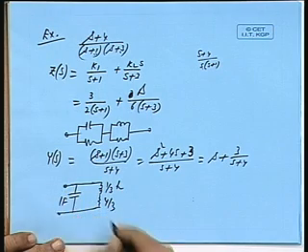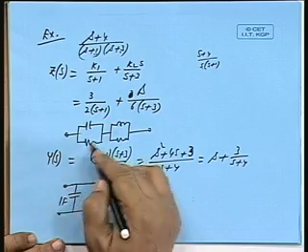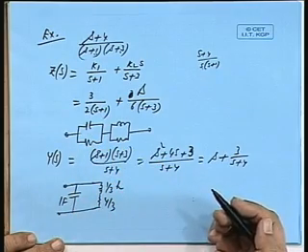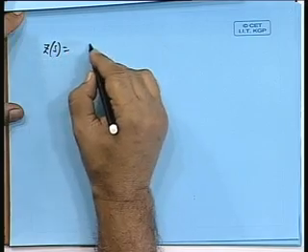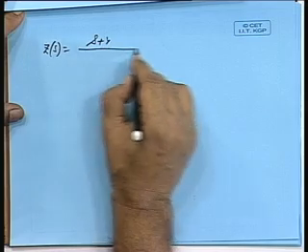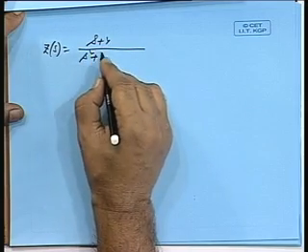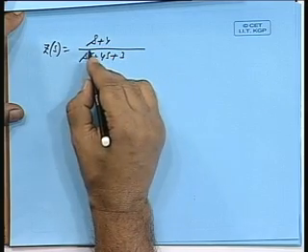Now, you see here you are having 3 elements, here you are having 4 elements. So, Y(s) and Z(s), you see the difference, alright. If someone goes for Cauer synthesis, ladder synthesis, let us see what it gives. Z(s) equal to (s plus 4) by (s squared plus 4s plus 3), is it not?